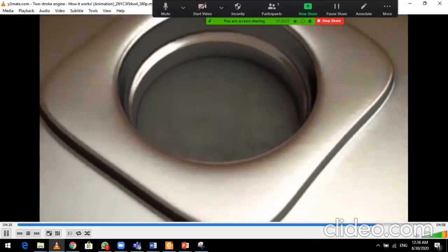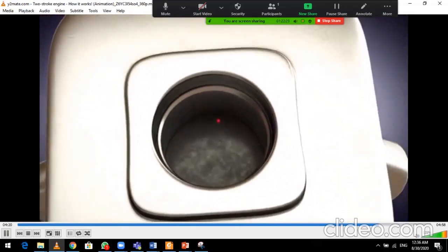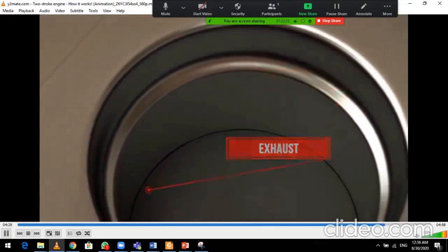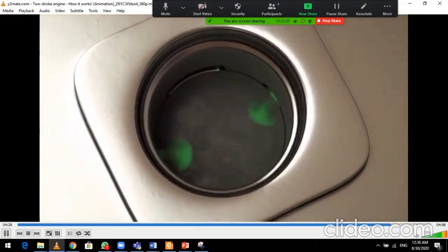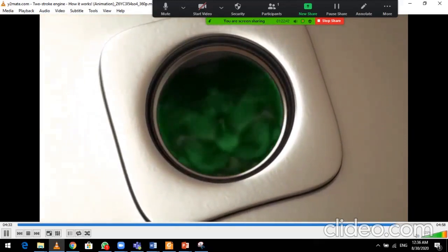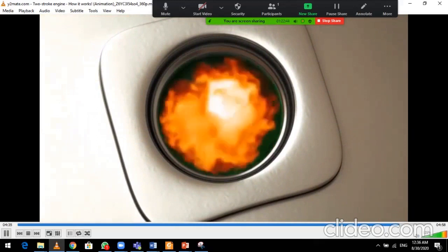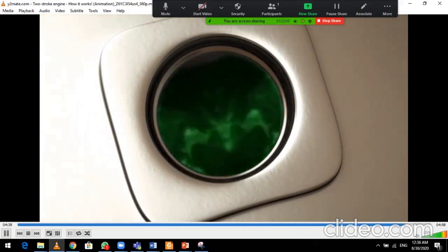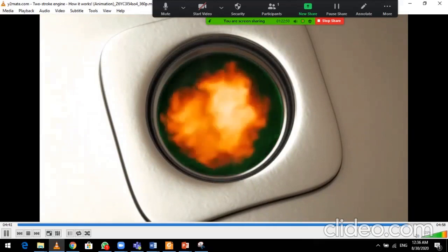The piston closes the transfer ports and exhaust port when it travels upwards. It opens them when it travels downwards. Through the transfer ports, the fresh mixture is promoted to the cylinder and filled from the rear to the front. When the spark plug finally ignites the mixture, the piston is moved downwards, and fresh mixture is able to flow in. In this process, the fresh mixture pushes out the exhaust fumes.